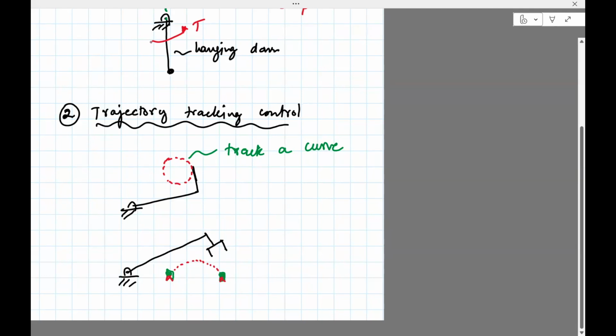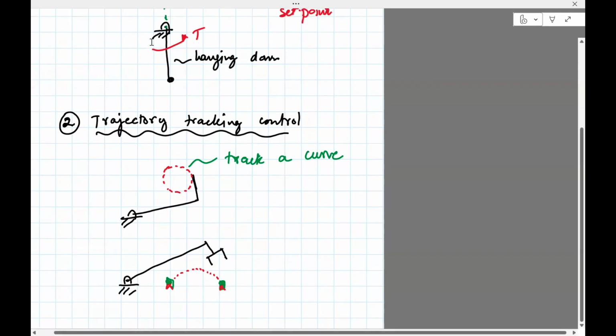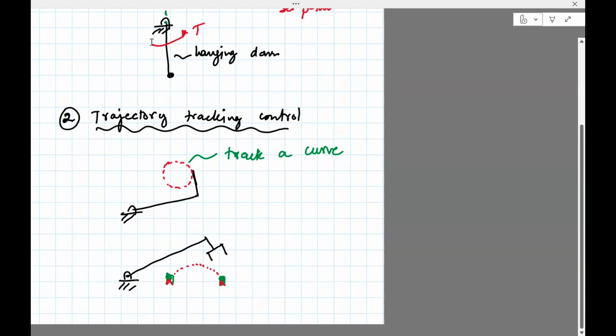Now, following that is non-trivial because, as I said, there's gravity fighting you, there's mass inertia. So what we'll do is see how to work with gravity and Coriolis force and all these things which I presented earlier, and make the manipulator move smoothly, following the trajectory without deviating from it, and working with the mass inertia and so on.